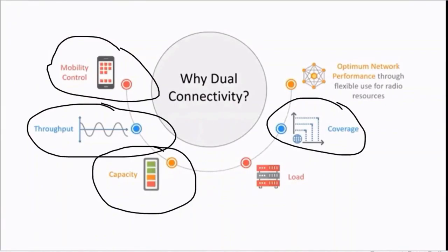But when we have micro cells or pico cells, you can typically provide coverage extensions with a better quality of service with the help of dual connectivity, right? Moreover, in case of 5G, we have various bands like low bands, mid bands, high bands. The lower frequency, say 600 megahertz, 700 megahertz, has wider coverage, because if the signal connection is not good, the service is not good, right?